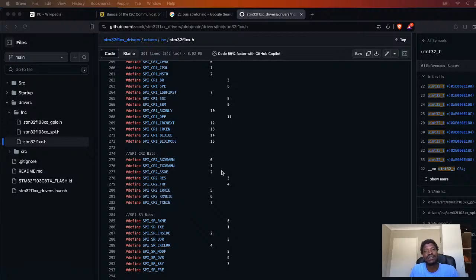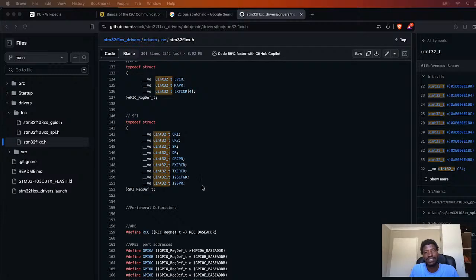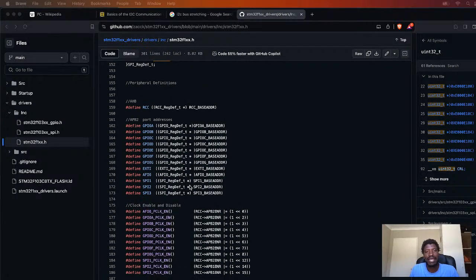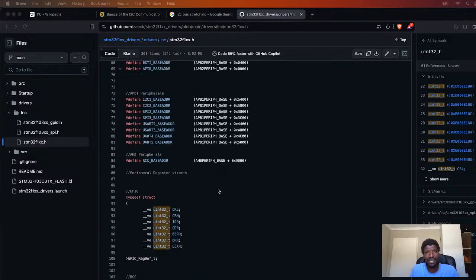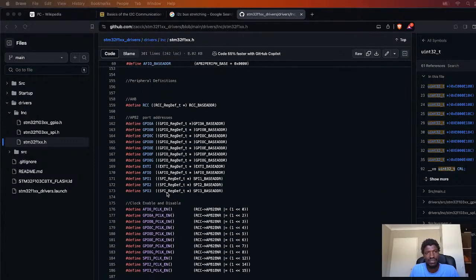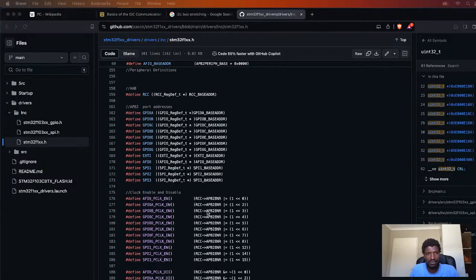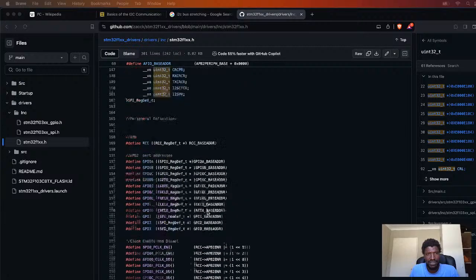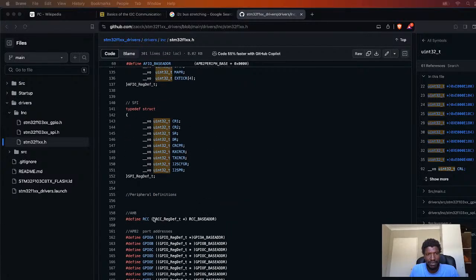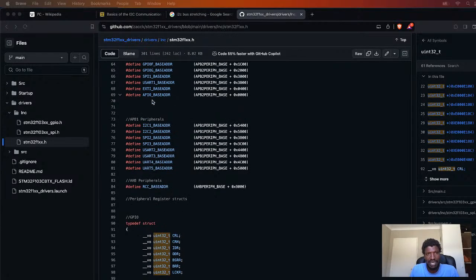But at the moment, yeah. So add the I2C register definition here, and then add some port addresses. I think we have I2C port addresses. So define the APB. It's going to be APB1. So we need to define APB1, AHB, APB2. Is there somewhere? Yeah, somewhere here.